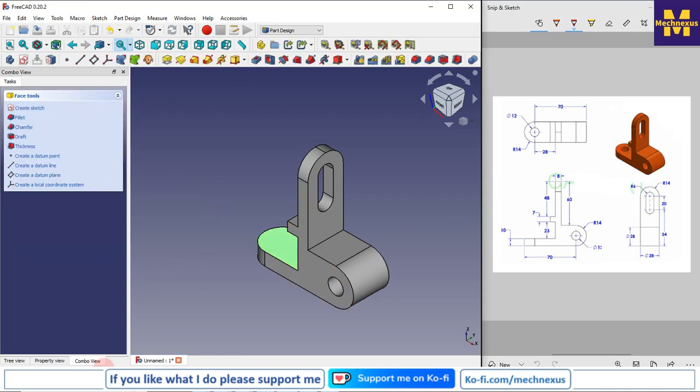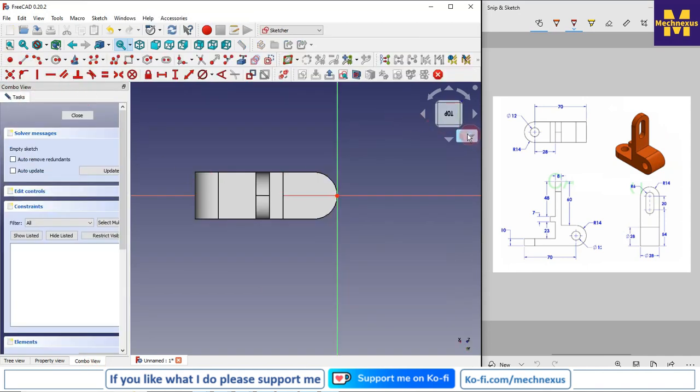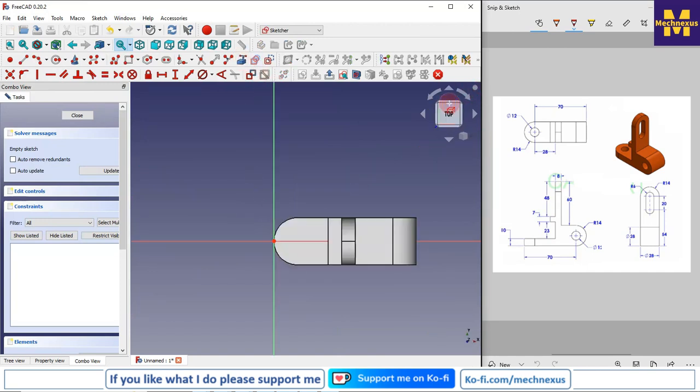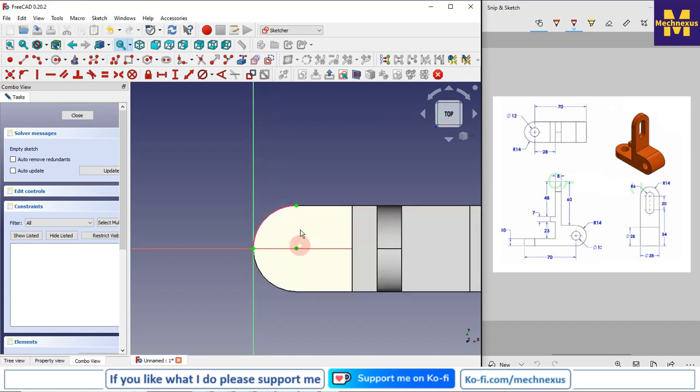Now I will select this face and I will create a sketch, and I will switch to the isometric view, and then I will go to the top and I will project the arc edge.